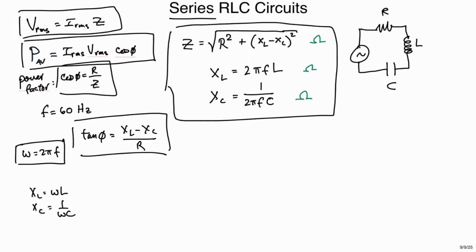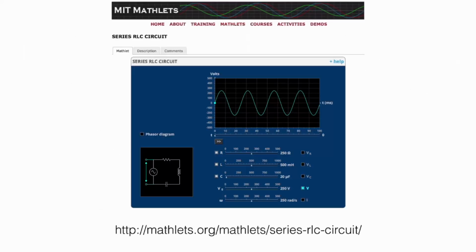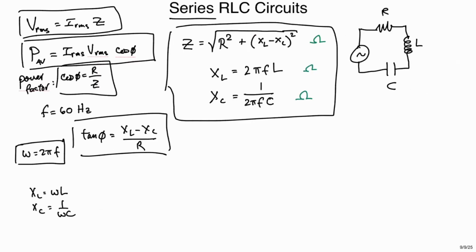Now, sometimes physics professors and textbook authors think they're being clever, and they say, well, the maximum output of a generator is 25 volts. Now, did they just tell you the RMS value? No, they told you the maximum value, so you have to convert to RMS. So maybe having these in your back pocket just to be able to get back and forth between them might be a good idea.